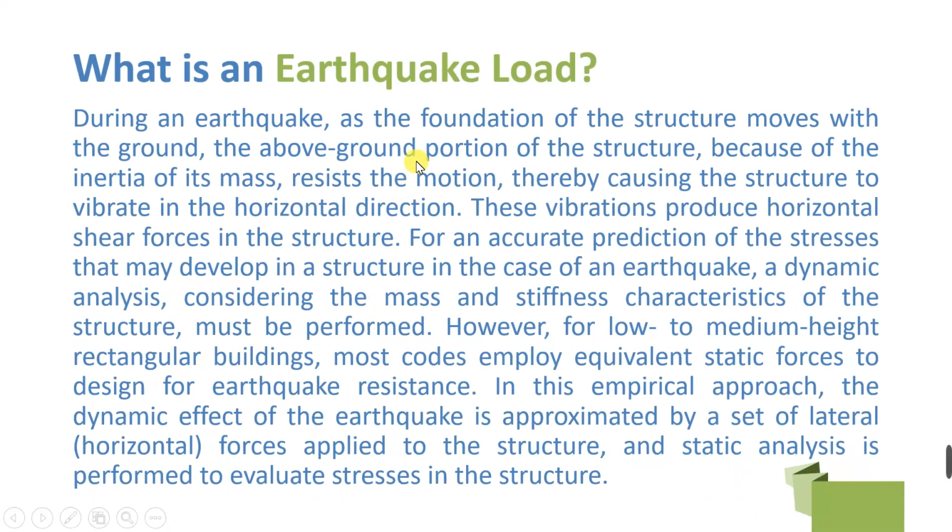Okay? So, again, during an earthquake, as the foundation of the structure moves with the ground, the above ground portion of the structure, because of the inertia of the mass, resists the motion, thereby causing the structure to vibrate in the horizontal direction. This vibration produces horizontal shear force in the structure. For an accurate prediction of the stresses that may develop in the structure in the case of an earthquake, a dynamic analysis considering the mass and stiffness characteristics of the structure must be performed.